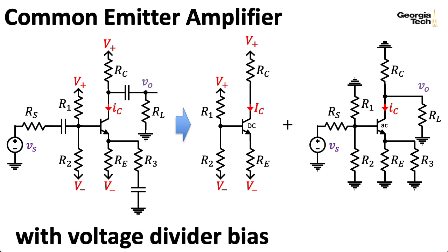Now, it looks like we did a lot of really complicated things, but essentially the answers popped out from a series of small individual steps. If you take a more standard approach where you take the small signal model and substitute it in and then derive all of the input and output impedances and the gains using that small signal model from scratch each time, this is actually a lot more complicated. Using these Thevenin and Norton equivalents looking into the terminals allowed us to basically write down answers essentially by inspection.